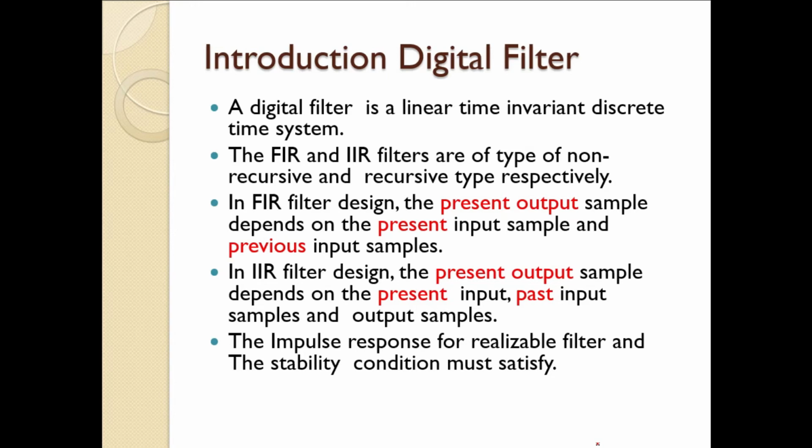Digital filter is a linear time-invariant discrete-time system. It has two types, FIR and IIR filter, which are the non-recursive and the recursive types. For the FIR filter, when we design, the present output depends on our present input or previous samples. For the IIR filter, we have the present output, y[n], and this present output depends on, which means equal to, our present input x[n],